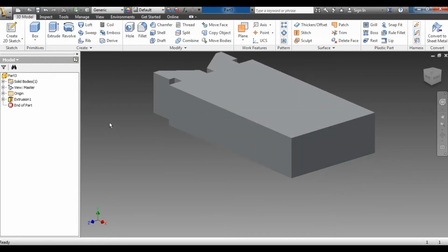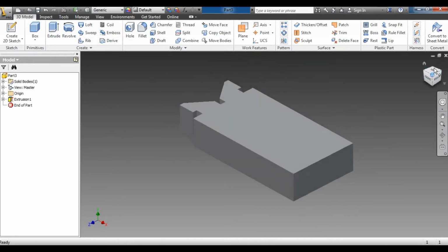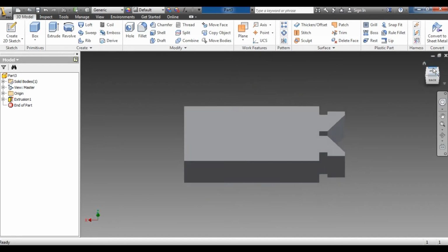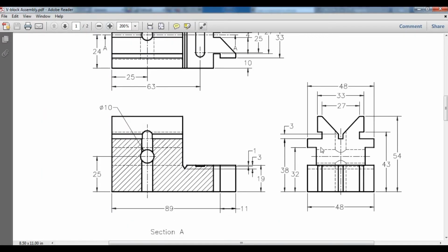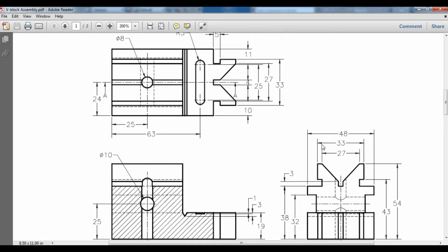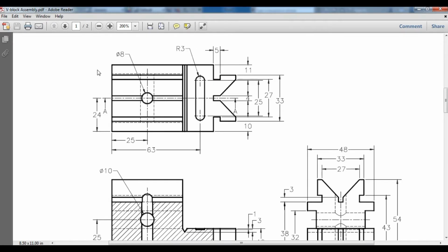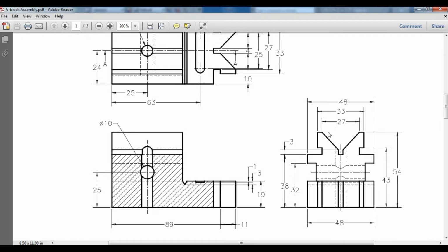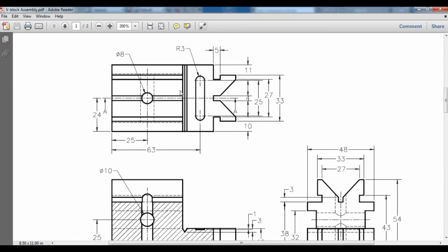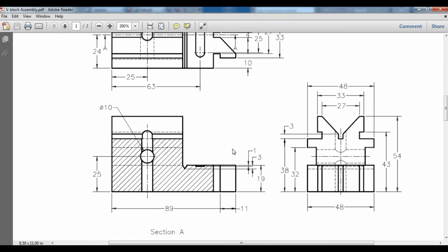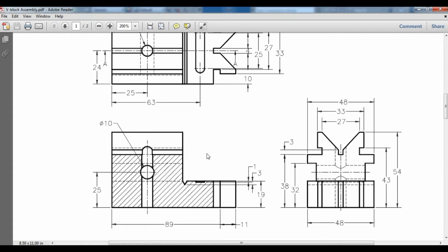And press OK. So this is a plane. So the next one is, I construct the plane. From the back side, okay, I'll take this as my plane, and I construct this one, and I took the extrude from this point up to over here, and that distance you have to find, what is the distance from here to here.